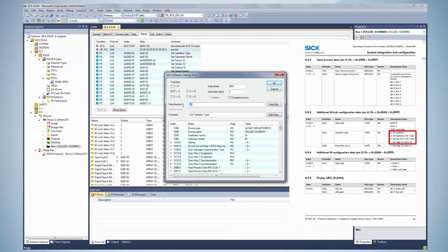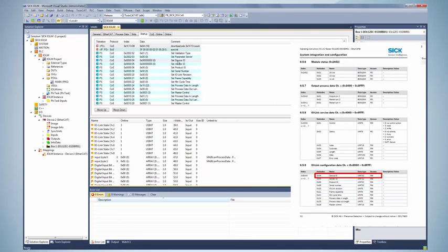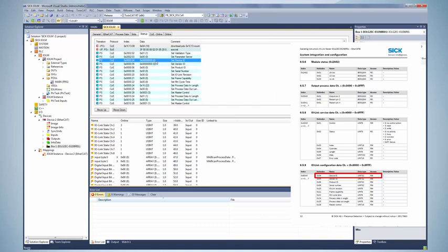In this example, the port is set in a way that it can only communicate with one specific I/O link sensor. This value is taken from the manual. Validation type 1 is required, which implies that the master checks during startup whether the sensor has the correct vendor as well as device ID. Now we switch to index 8000 subindex 4 and set the device ID of the connected sensor. The device ID is taken from the IODD file.